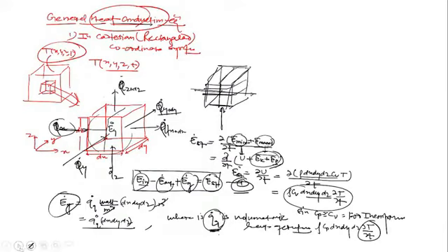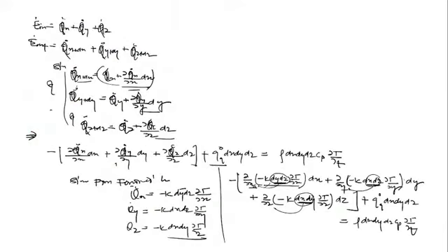So now, my dear student, from this equation, if I take the area outside, then the resulting equation that I will get has one limitation. What limitation is there? That it can be used only for constant area, where the area must be uniform. Clear? If I am taking these terms outside the differentiation, it means the resulting equation is valid for only uniform area. You can't use these equations for a geometry where the area is going to vary. So whatever simplified equation I will get here can be valid only for uniform area. That you must know.